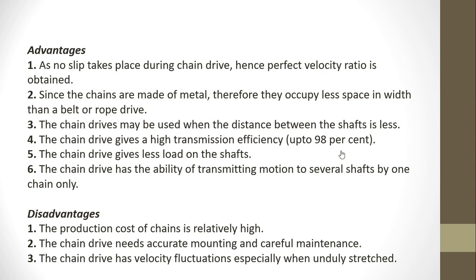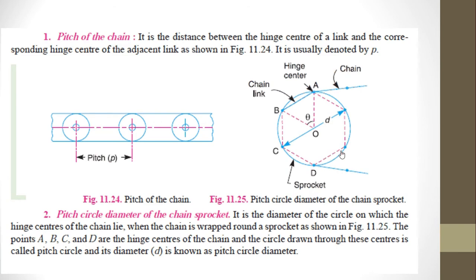Disadvantages are that because they are made of metal and there is an assemblage, they are quite costly. And they need proper maintenance and proper assemblage. Without that, they will not work. And secondly, if you have not maintained the tension, then you will see problems related to velocity fluctuations.